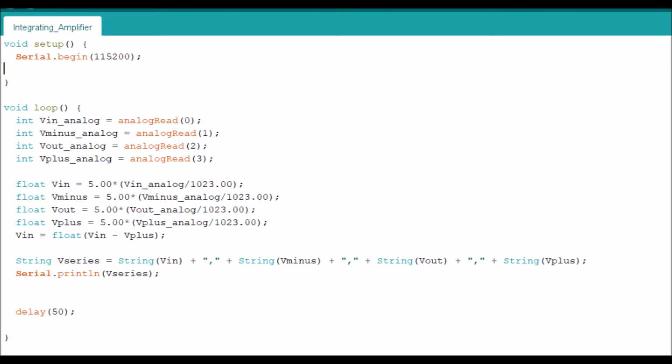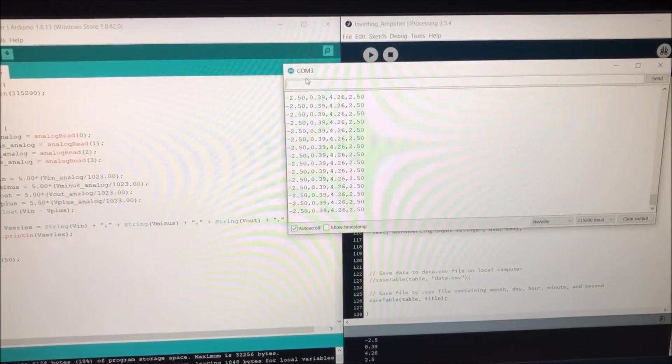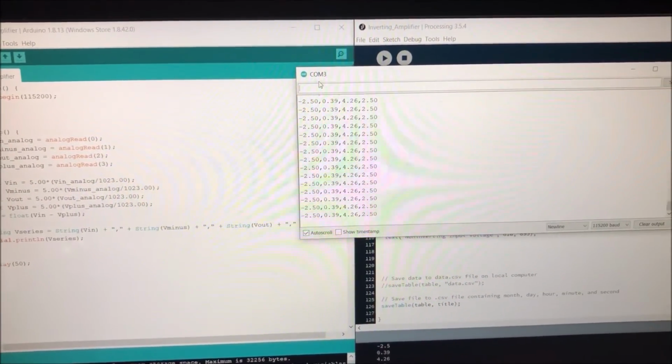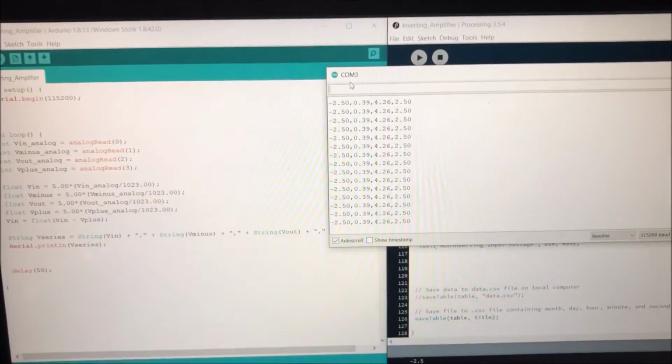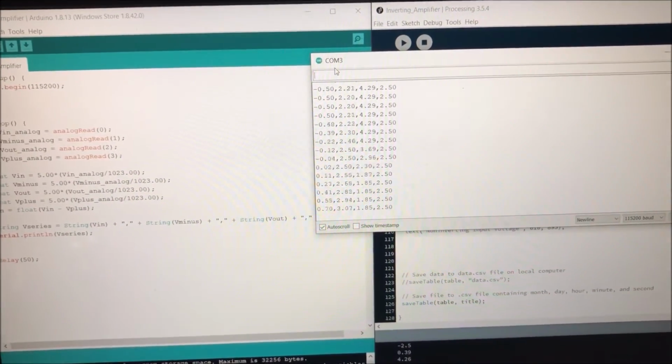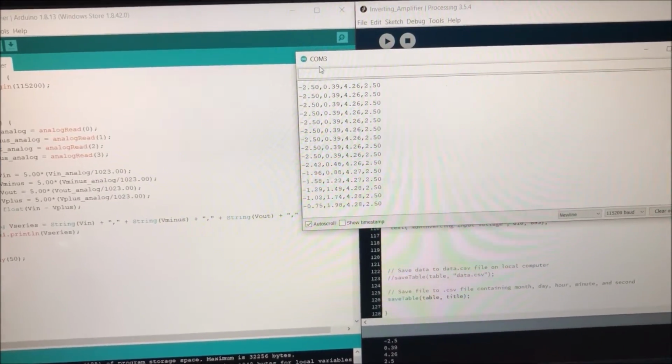The input voltage also becomes the difference of itself and the ground state of 2.5 volts. The input voltage now ranges from -2.5 to 2.5 volts. The inverting input voltage stays slightly more compact within the 0 to 5 volt range due to its space as a voltage divider. The output voltage plateaus at 4.25 volts and 1.9 volts.